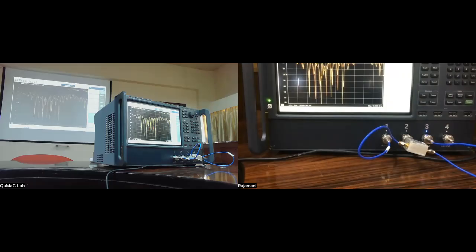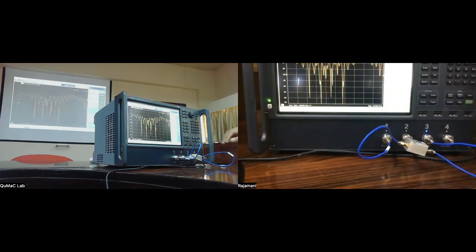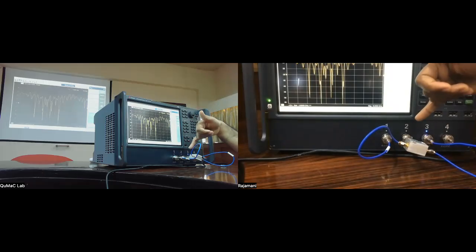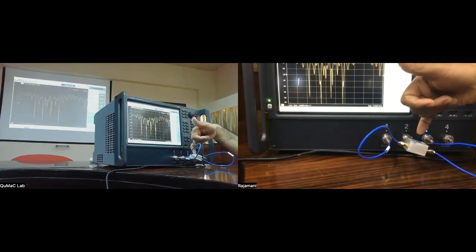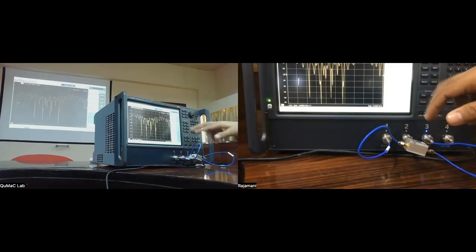So we have looked at reflection on all three ports, and it's verifying that it's a matched 50 ohm device. It's absorbing the power on all the three ports. Now, come back to data. We'll now start looking at the transmission in the normal direction, which means to the output from the input. So the input port is 2 and the output ports are 1 and 3. So we'll source from 2 and measure at the output at 1 and then 3.